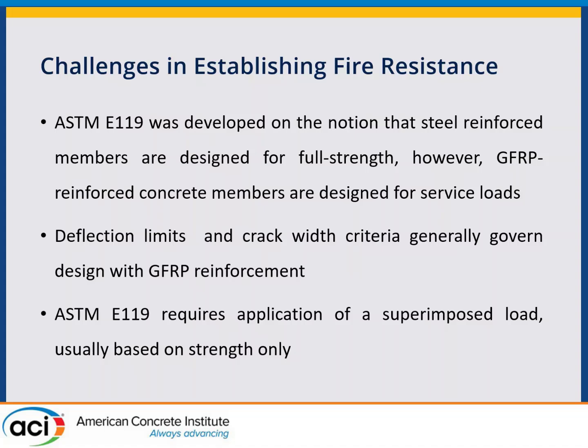So of course, we design for serviceability, and we also have restrictions on the strength. We've actually just increased it to 30% from 25%, so that for the long-term stresses in the bars, we never expect there to be more than about 25 or 30% of its actual tensile strength in normal circumstances, which is very different from what we allow for steel.